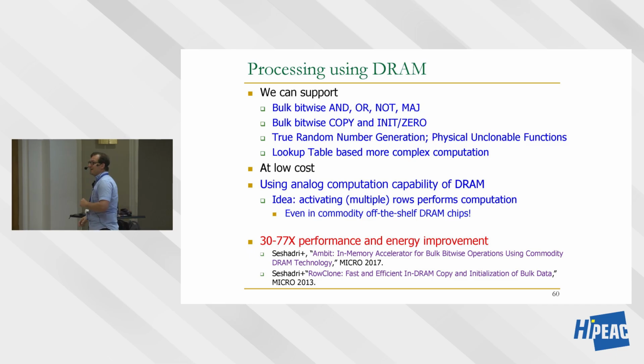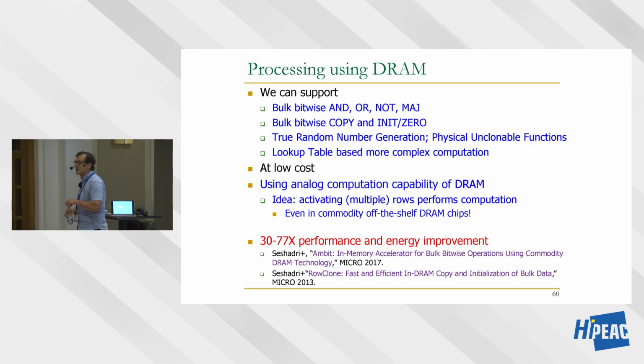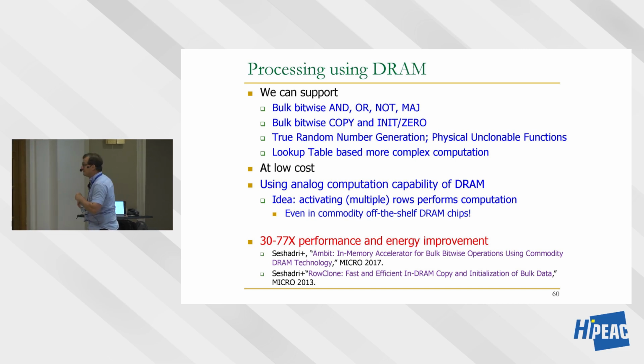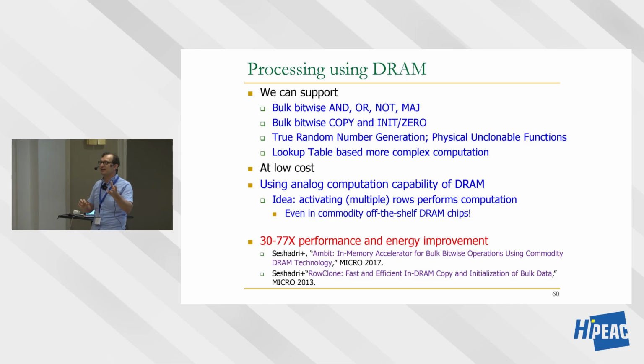Okay, we still have time. Basically, we can support a lot of things in DRAM by modifying the DRAM a little bit. And also, even existing DRAM chips support this. So you're lucky to be sitting here in 2024 because there are actually very new results in 2024 that show that even existing DRAM chips support some of these operations that we envisioned by modifying DRAM. And that's really fascinating to me because memory is designed as memory today, right? People use it as loading and storing data. But if you actually think about it slightly differently, you can do computation in it, even existing DRAM chips.